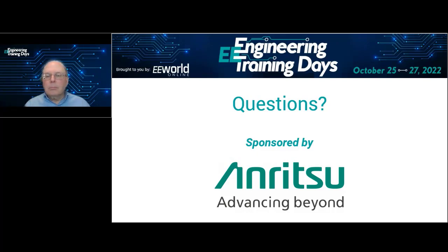So that's an excellent question, Martin. A calibration can remain valid for a long period of time, and I don't want to use the word indefinitely. It depends on how stable the cable antenna analyzer or vector network analyzer is, but it also depends on the ambient temperature. So when we do calibrations on our products, whether it's a cable antenna analyzer or a vector network analyzer, at the moment calibration is performed, we are capturing temperatures inside the instrument, and that becomes part of the calibration data. And so we characterize our products across a certain temperature range.